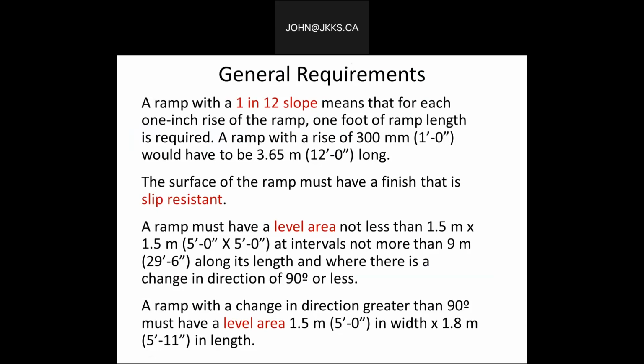The surface of the ramp must have a finish that is slip resistant. Now, this isn't a code requirement. I call it a safety requirement. It just makes common sense. We saw snow earlier in the picture, and we saw snow on the ramp, and certainly people can get out and clean away the snow. But we have to think about the safety issue and the potential to minimize that by having a more slip resistant surface.